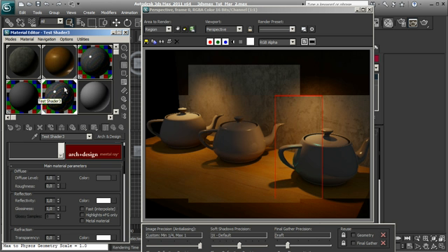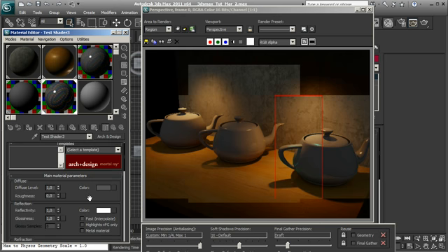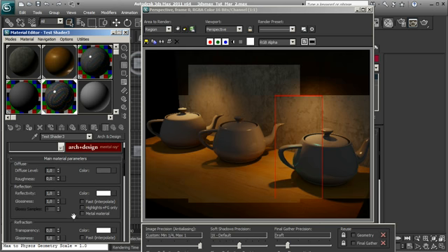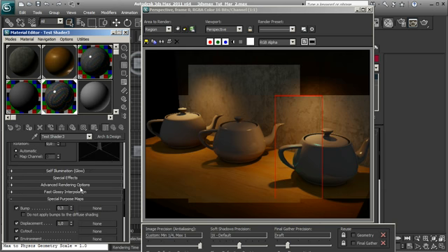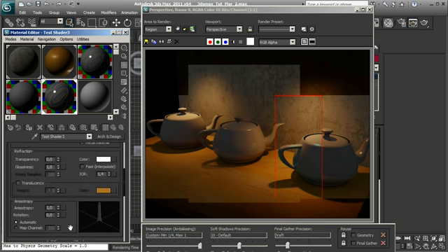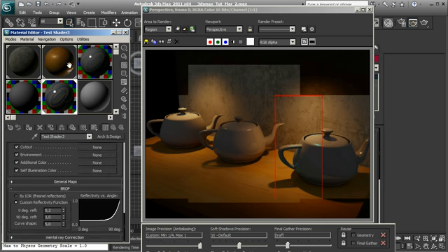Obviously, you can use a map to control the coloring for the reflection. Let's see what happens if we have, for example, a glossiness. But to do that, I'd like to go just a little bit over the control over the BRDF curve. So let's go there in the BRDF, and you see that we have the possibility to add a typical Fresnel reflection using the IOR value, or we have the possibility to control manually the reflection.